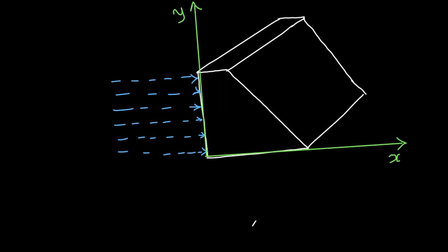Now, one question that you may be asking is, where does the thickness actually increase? You see that there is more material at the bottom compared to the top. One of the reasons is that the hydrostatic pressure is going to be greater at the bottom, so you want to put more material at the bottom. Good. Now, what is the plane that you are going to analyze? Again, you are going to analyze this particular plane.